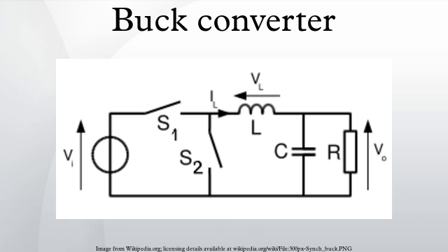Typical motherboard power supplies use 3 or 4 phases, although control IC manufacturers allow as many as 6 phases. One major challenge inherent in the multiphase converter is ensuring the load current is balanced evenly across the n phases. This current balancing can be performed in a number of ways.